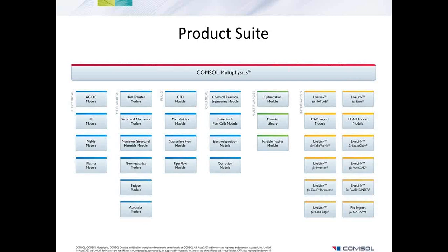Oh, okay. So a sort of follow-up to that is one here by Fred, who wants to know if you can introduce an eccentric load, say if you had an error in machining. Absolutely, and this is where COMSOL is really flexible. As far as introducing the eccentricity, one thing that comes off the top of my head is that in COMSOL you can type in any quantity, whether it is a material property or, in your case, force, as a function of the XYZ coordinate. So if you know the offset as far as the eccentricity is concerned, you can type in such an expression which is a function of XYZ coordinate, and that's pretty much it.